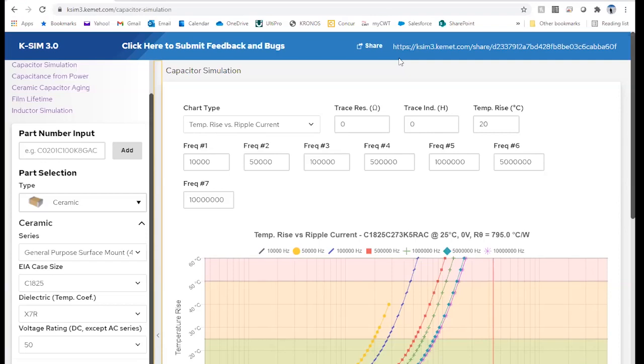The last question we have for today is, moisture concerns still have to be adhered to in a polymer cathode solid tantalums? Yeah, so the tantalum polymer is going to be a MSL3, so you do need to worry about the moisture. And I think in the data sheet we should have under storage and handling, there should be some kind of description on how those parts should be stored and handled. They do come in, I guess, MSL bags or packaging. So I guess if you're storing them in those, you should be fine. But if you take them out, there are specific concerns.